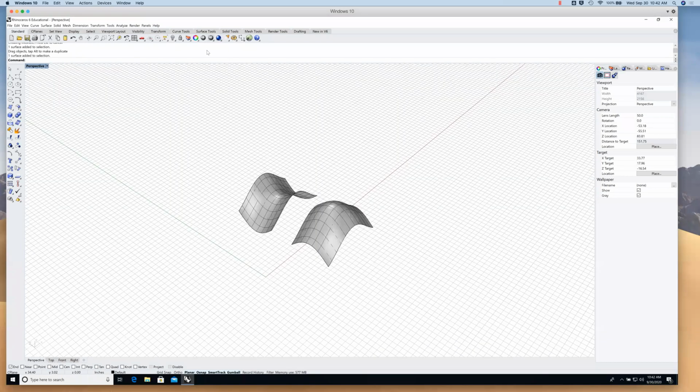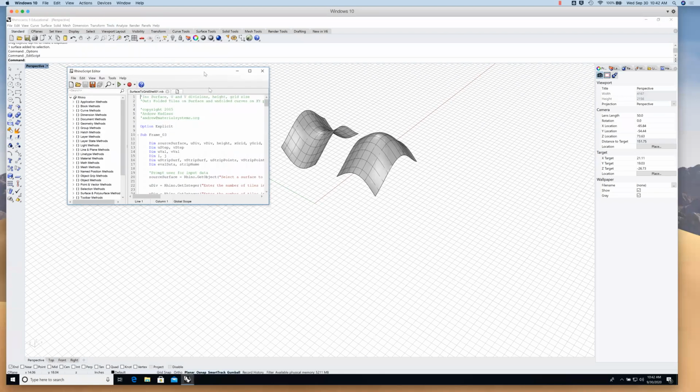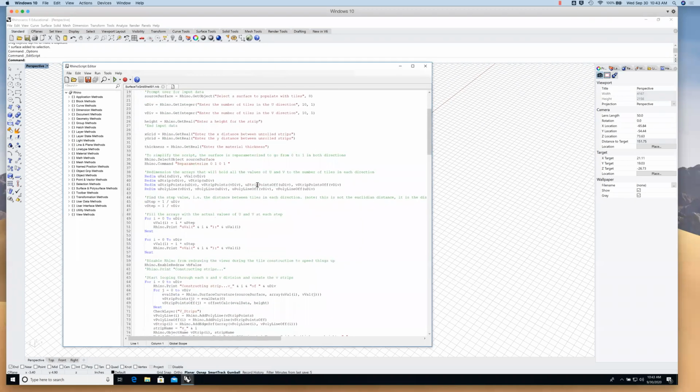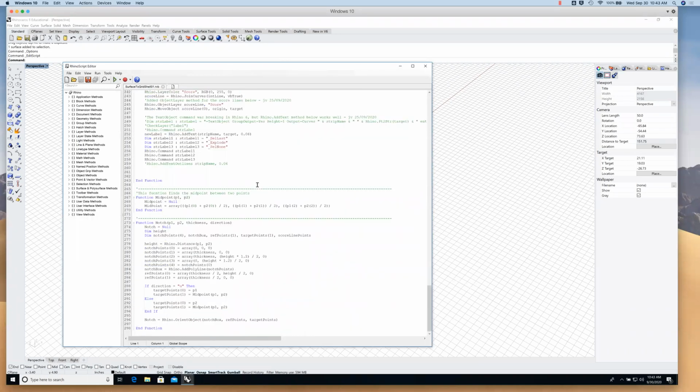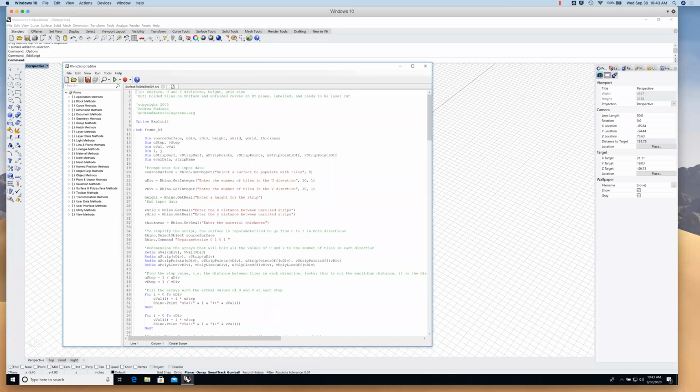Now I'll show you, and I think I have this almost tweaked enough that it'll work for you. But we're going to do some stuff in Grasshopper, but at the end of the day, I'm also going to give you a Visual Basic script. This is from my buddy, from a long time ago, and he wrote a script that takes a surface and breaks it down into a grid shell and takes all the ribs and populates it with ribs and then unrolls them and then labels them and puts notches in them for you. So we'll do some things in Grasshopper and then I'll give you the shortcut here.